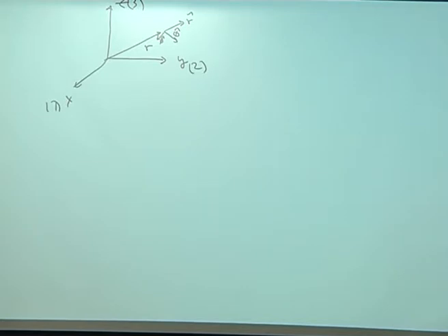And so TRR is the stress on the r hat plane, which would be perpendicular to this plane here, in the r hat direction. It's just like the regular stress definition, except here it's in spherical coordinates. The stress in the r hat plane in the r hat direction is normal to the interface, right? So it's a stress normal to the interface. If you put a hat on this, it's stress normal to the interface.